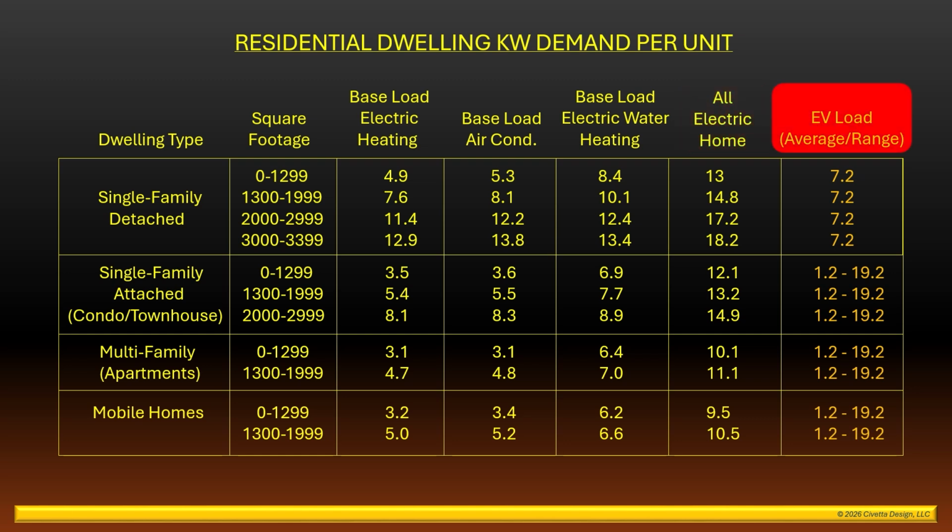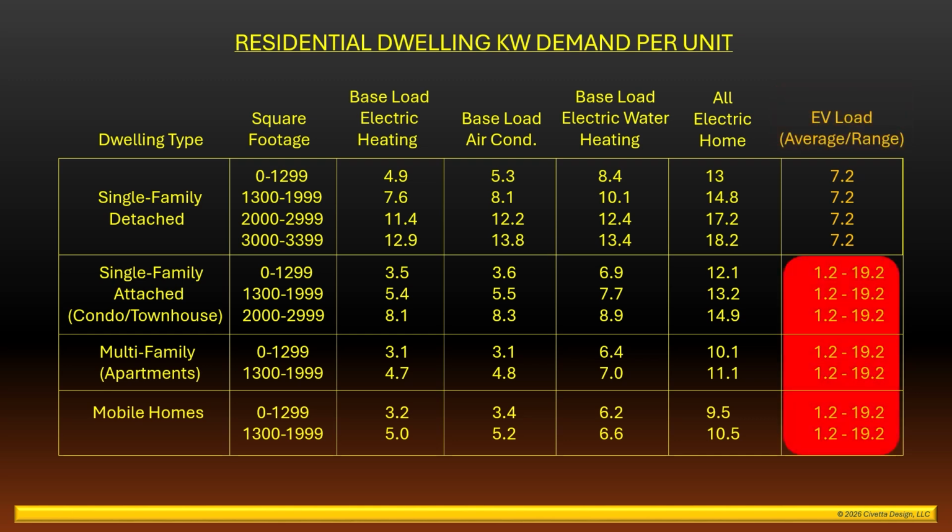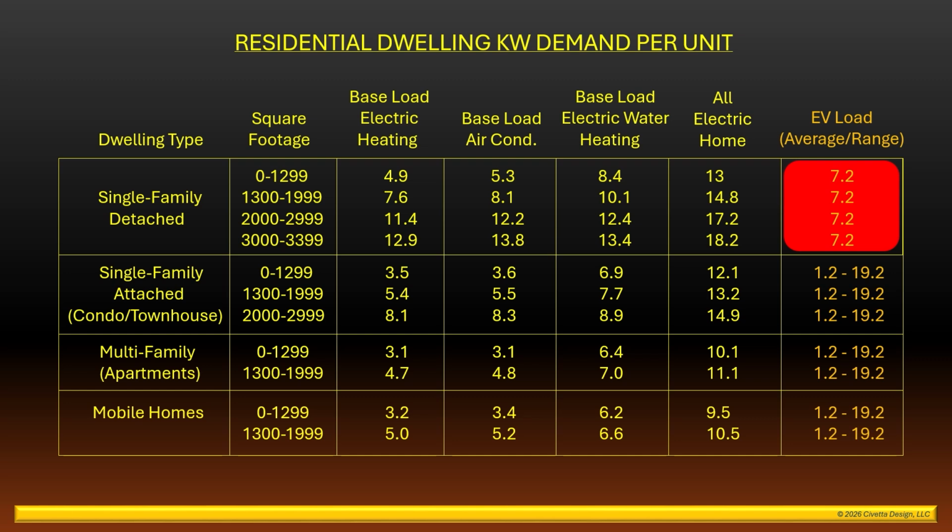As of January 2026 in California, in addition to the base load selected, electric loads need to be added for all new homes that will be required to include electric vehicle charging. Depending on the actual type of EV charging installed, this can fall in the range shown of 1.2 to 19.2 kilowatts. If the actual EV charging load is known, that value should be utilized. If the EV charging load is not yet known, the National Electric Code recommends the value of 7.2 kilowatts to be used. Let's look at a simple example.